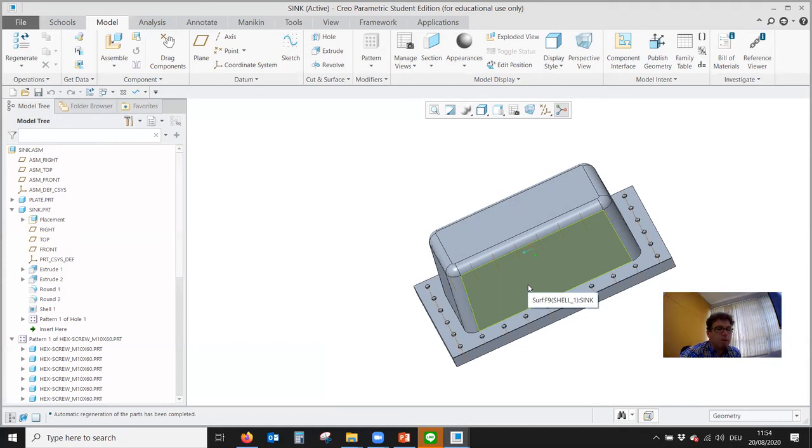And if you do that well, then your assembly is super stable. Sometimes if you have an assembly where you reference real part on part surfaces and you change some part, then your assembly will explode because all the references are missing. And with the skeleton model, that is one way to avoid that. And in the real industries, for example, if I wanted to do a CAD model of a train, something with thousands of parts and sub-assemblies, I would definitely have some sort of skeleton model to do that.